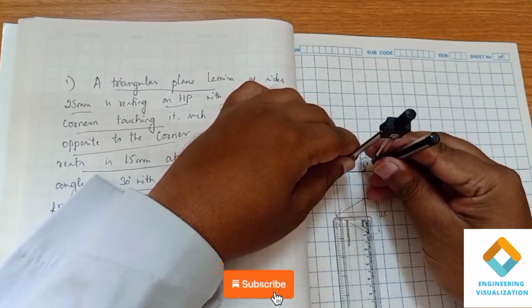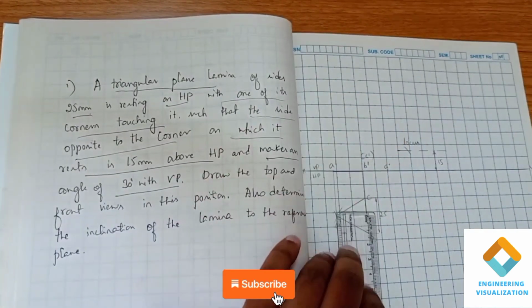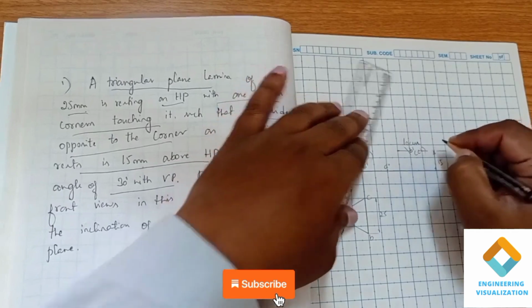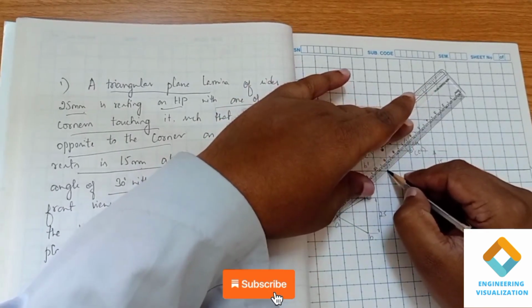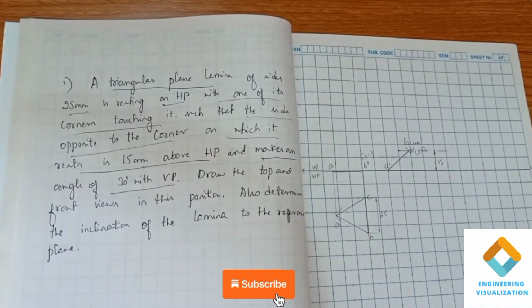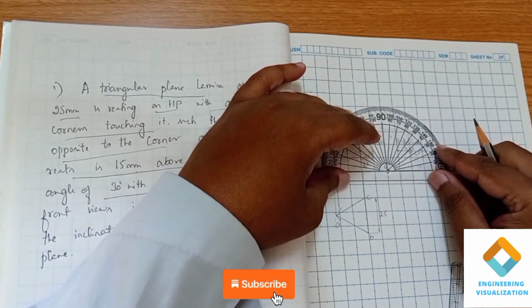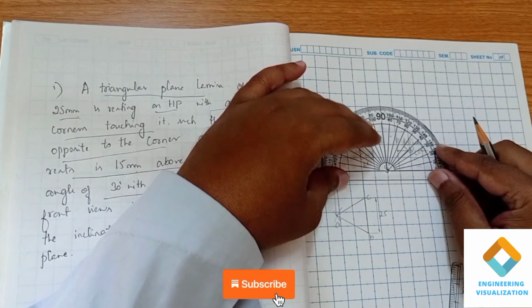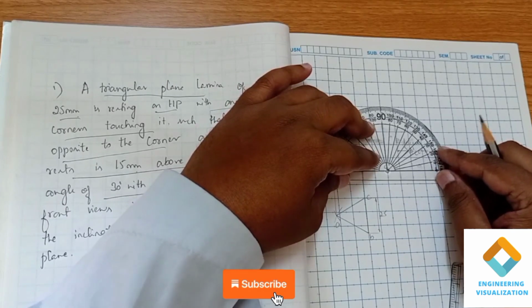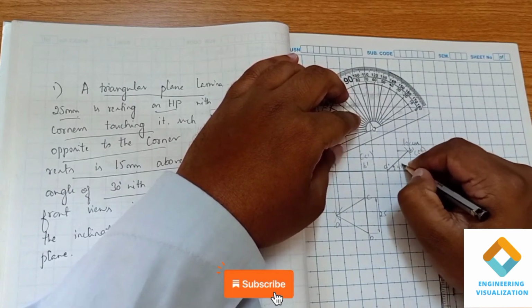Now you see this question, they have mentioned only the distance here, and they have not mentioned how much angle of inclination. Instead they have mentioned only this sentence, that is the side opposite to the corner on which it rests is 15 mm above HP. So this is the side which is opposite to the corner. In this second position, we are inclining this side at a height of 15 mm above HP. Inclining at a height means we are inclining this front view only, right?